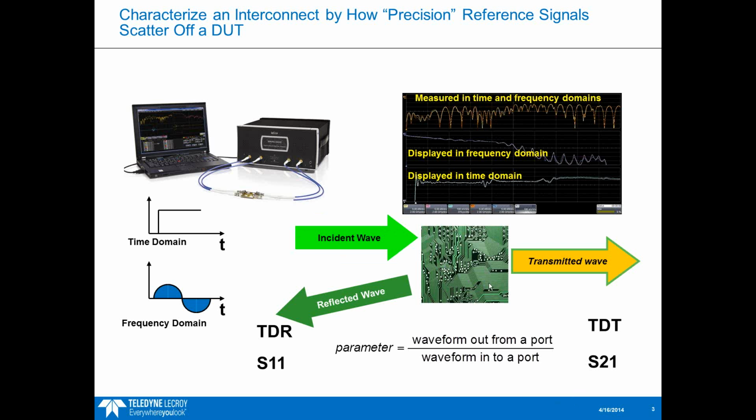A much easier way to do it, and cheaper, and works a lot better overall, is to do a calibration. You have these different structures that you measure, whose behavior is known ahead of time. By measuring those, we can create some compensation coefficients, basically, to correct for any imperfections in the reference signals.